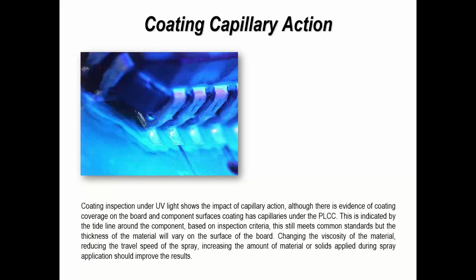Capillary action. This is kind of interesting. I've made a couple of videos on this particular subject on YouTube, which you can go to my YouTube channel and see. But capillary is where you apply a beautiful coating, consistent to the board, but it actually is drawn underneath the component. So what you're looking at here is not a coating which has been applied manually with a paintbrush around the surface, which it looks like, to be fair. What's actually happened is the coating thickness has been drawn underneath the package.